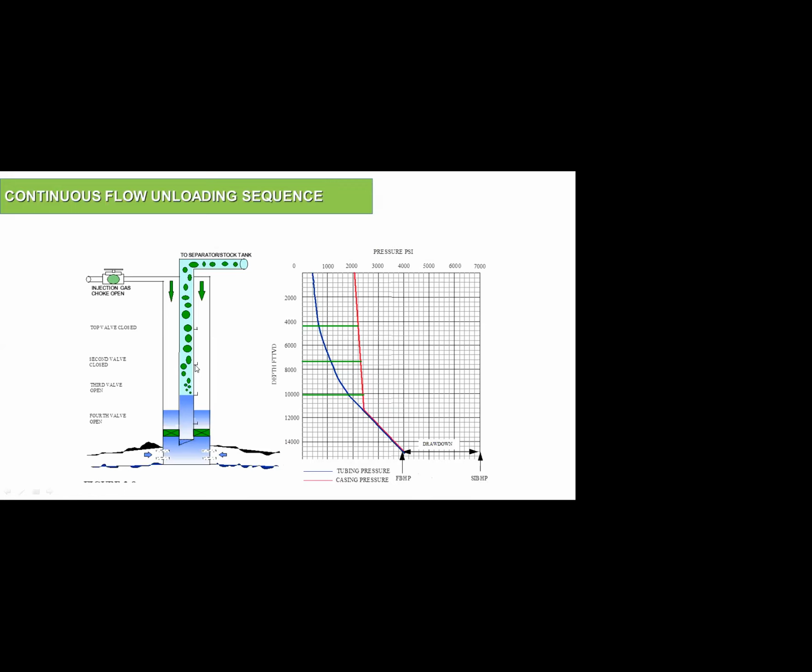So if we again try to conclude this, each time I'm injecting through a certain valve, decreasing the gradient here, then I go to the lower valve until I reach certain pressure limits. When this valve is closed and I inject only from this valve, then I go down to this valve and this valve. I have two valves open. Then a certain limit comes when I inject only from this valve and this valve is closed until I reach my operating valve. In this case, only this valve is my operating valve, so it's okay. So this is the case.